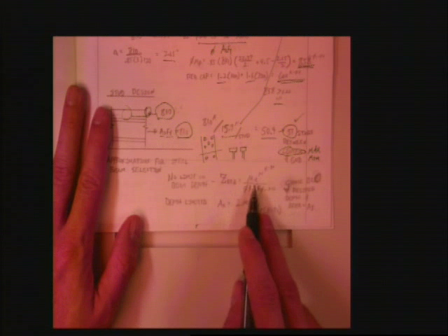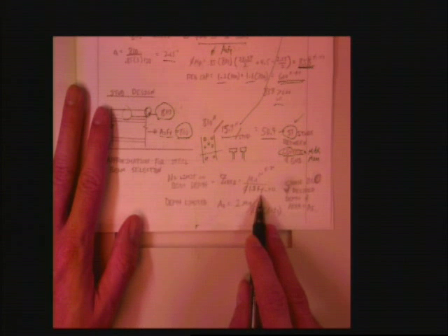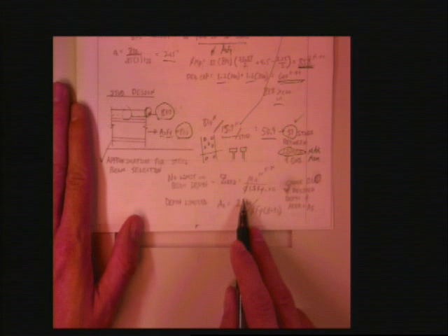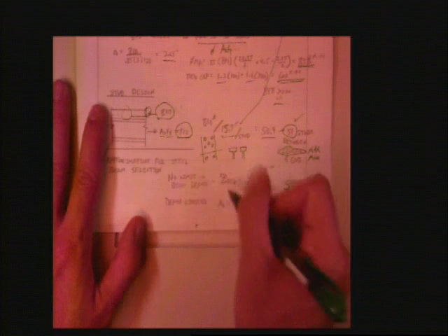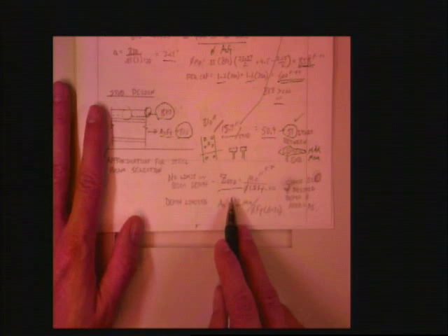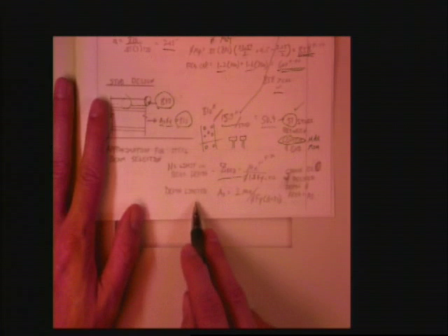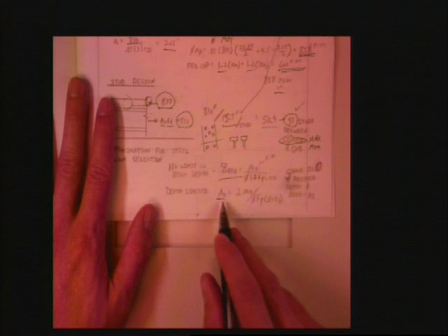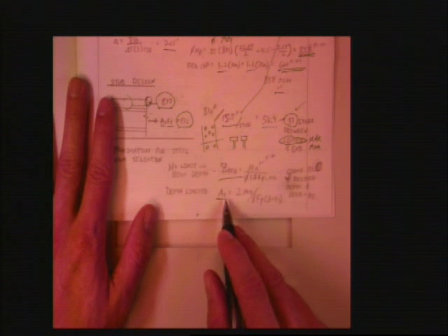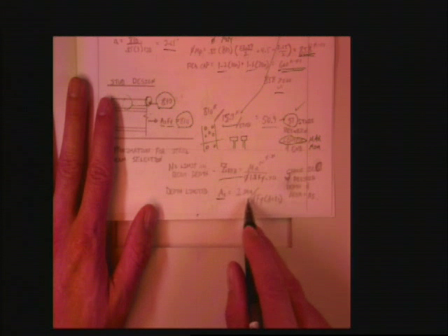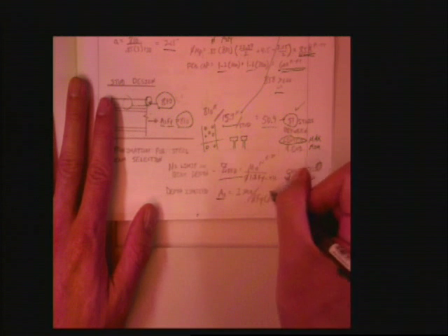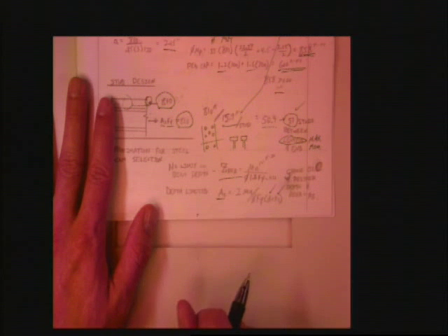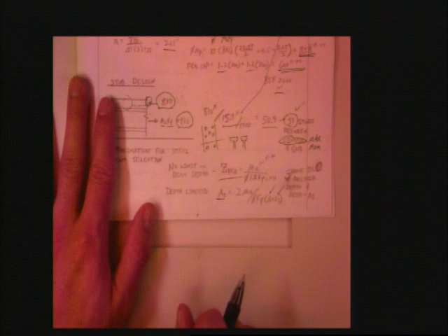Put your maximum moment in kip inches, put your Fy in ksi, you put your phi factor in, which I believe is 0.85 in this case, and it will tell you your Z required, and we're going to show you how this works coming up. It's pretty awesome. If the depth is limited, then the area of steel you have to provide is a good estimate. Not saying it's accurate every time, but it's a good first estimate. It is 2 times the maximum moment, again in kip inches, divided by phi Fy d, where d is the depth of the girder, minus t sub s, the thickness of the slab. Make sense?